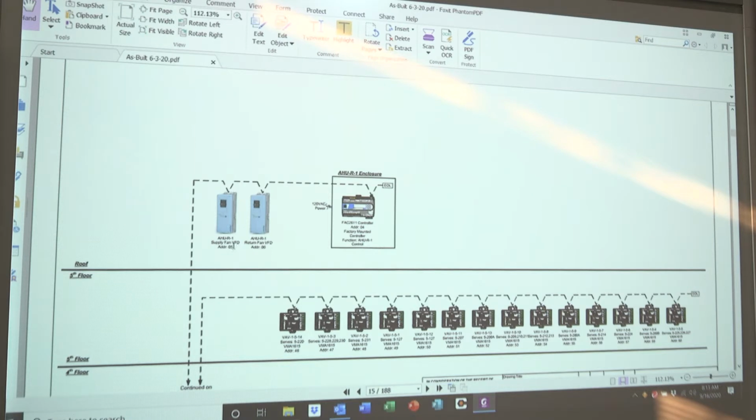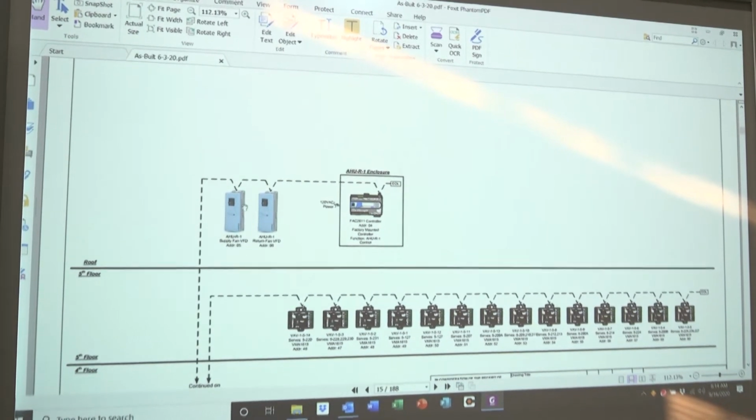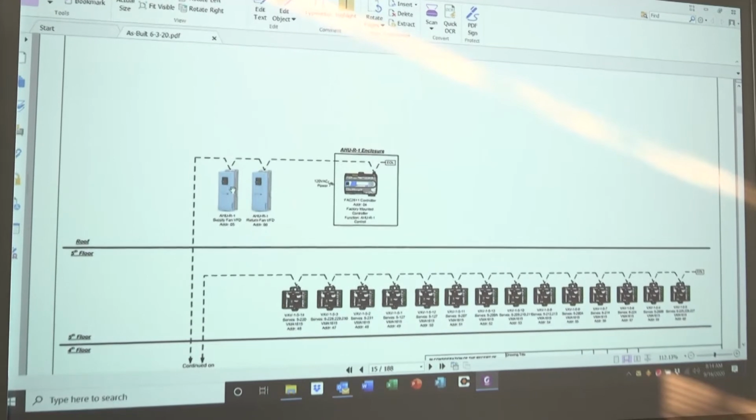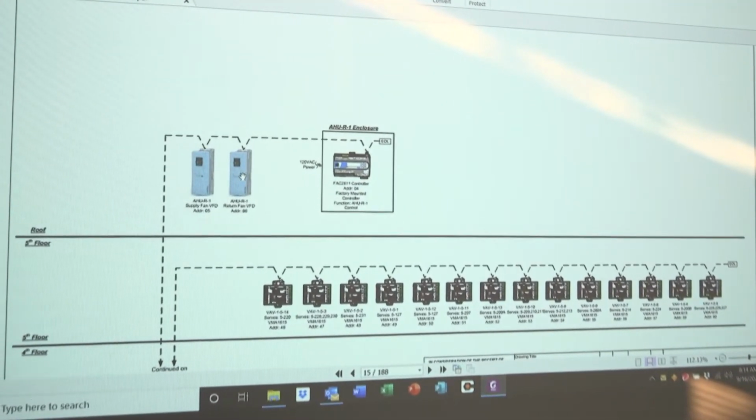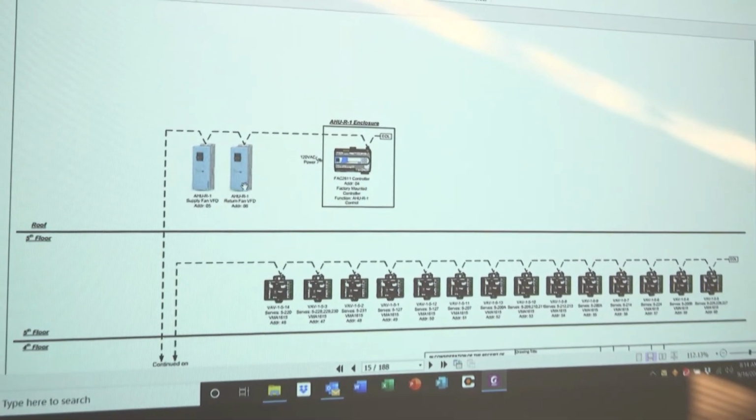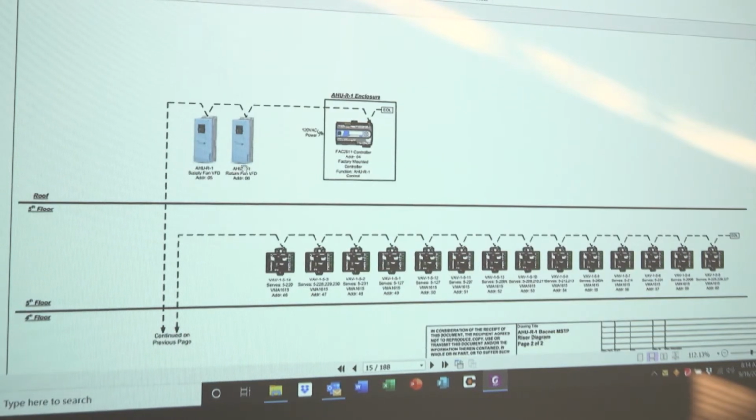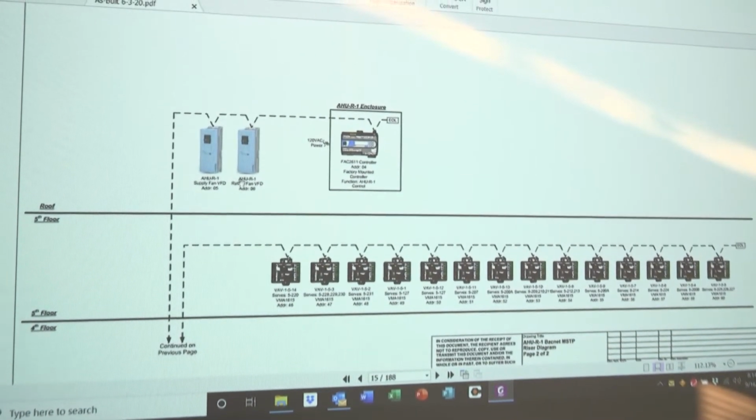Again, we talked about yesterday single point power entry, and then the supply fan VFD and the return fan VFD. Both of these VFDs, there's one VFD for 2 supply fans, there's one VFD for 2 return fans. They operate at the same speed, and they're controlled by the same VFD. There are start-stop status commands given to these fans from the BMS system based on the operation of the unit and differential static pressure set points that are controlling these speeds.